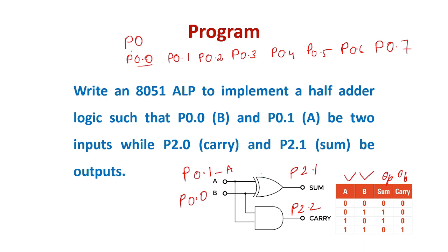So you need to perform it with a byte oriented instruction, which works bitwise but operates on the entire byte, that is 8 bits. But we are interested in the least significant bit, so that specific bit you need to transfer to the accumulator.